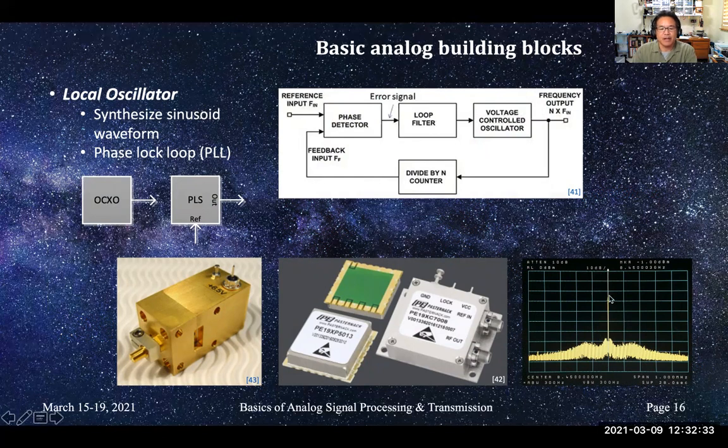Now, this is a spectral response of a CW waveform that we use on the SMA for one particular antenna. This one's at 8.45 gigahertz. It's like the first plot that I showed in this talk. It's frequency versus power, and almost all the power is contained here. There's some residual noise. The shape is indicative of the phase lock loop bandwidth. You can see this kind of a hump that occurs here.